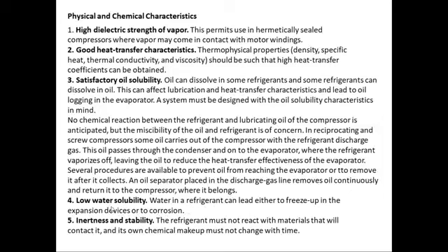Low water solubility. Water in a refrigerant can lead either to freeze up in the expansion device or to corrosion. So water is a no-no for your refrigerating circuit. If it gets into it and travels down to the evaporator, it will freeze. It will become ice, so it will choke your evaporator. So you don't want it there. And if it goes to any other parts, it will cause corrosion. So that's why low water solubility is required.